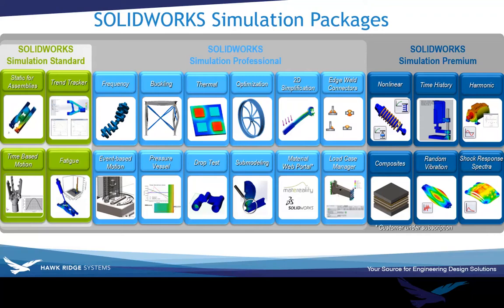Right? But once we decide that we do need to utilize a nonlinear solver within simulation, we need to graduate to SOLIDWORKS Simulation Premium. And that's the package that allows us to do this nonlinear type of problem, in addition to some other advanced problems like a dynamic problem. But in terms of packages, if you have a nonlinear problem and you want to use SOLIDWORKS simulation, you have to graduate to Simulation Premium, which again gives you everything that you see on your screen here.